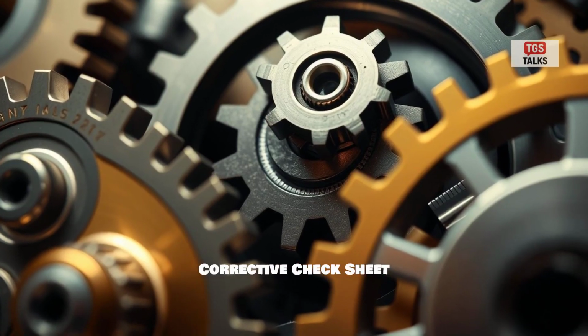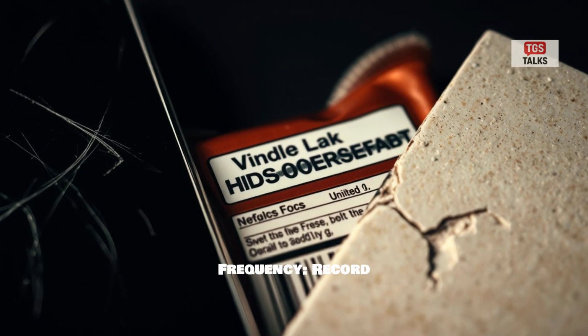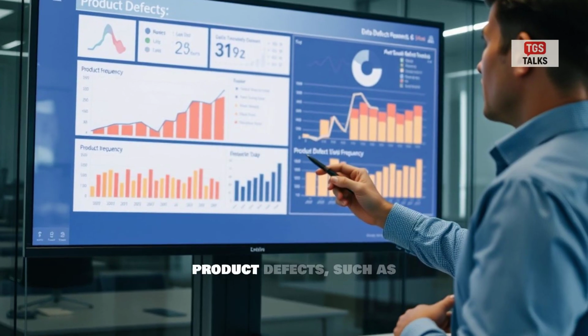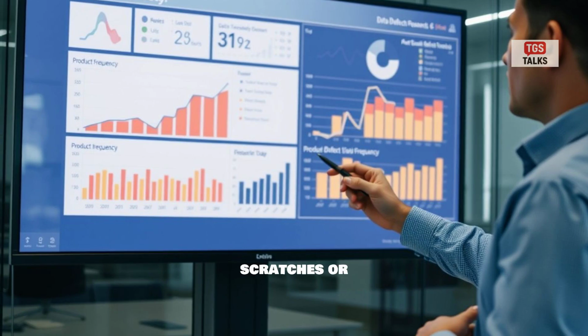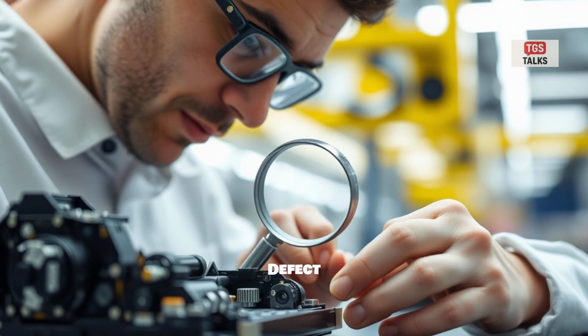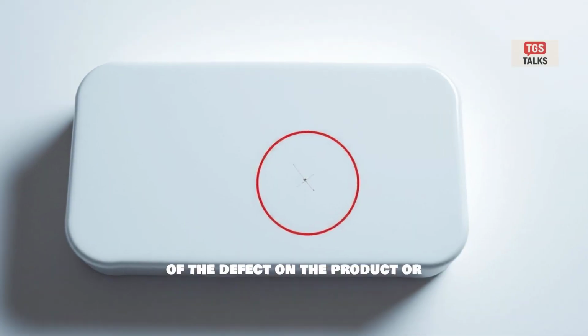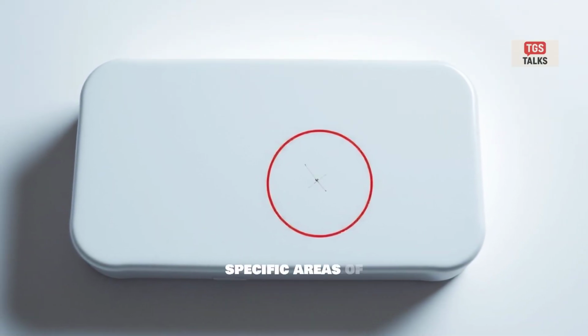Corrective check sheet checkpoints. Defect type and frequency: record the type and frequency of product defects, such as scratches or mislabeling, to identify common issues. Defect location: note the location of the defect on the product or component to pinpoint specific areas of concern.